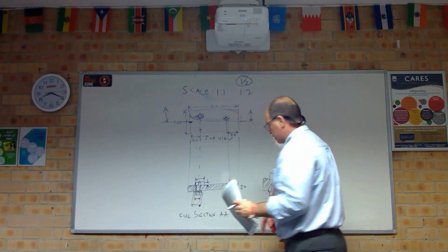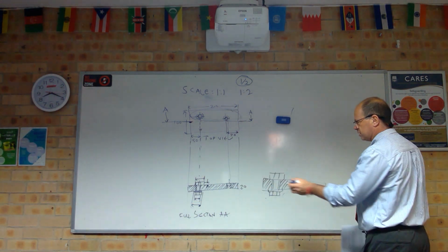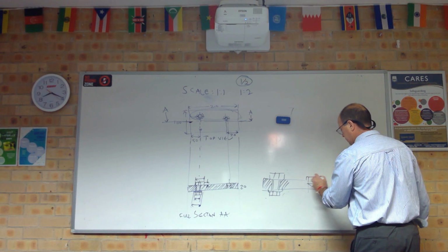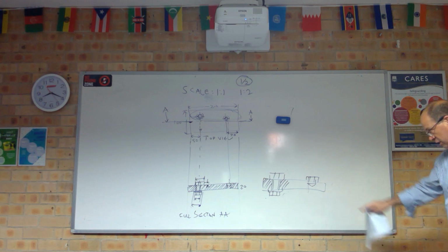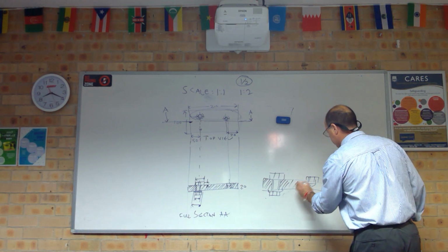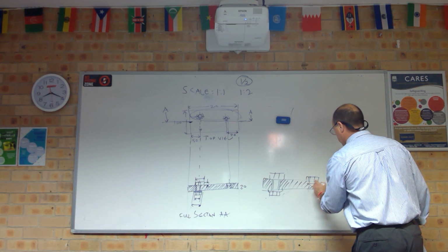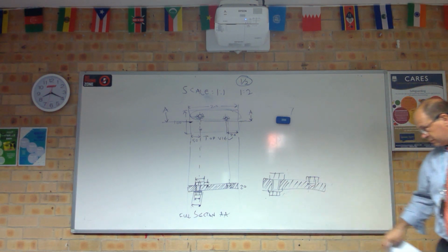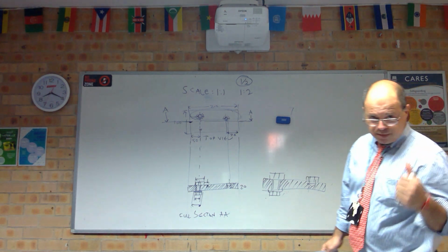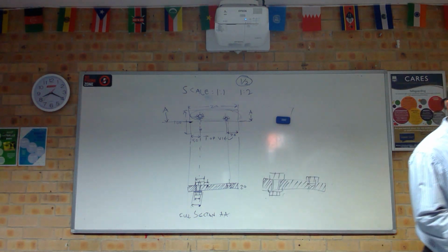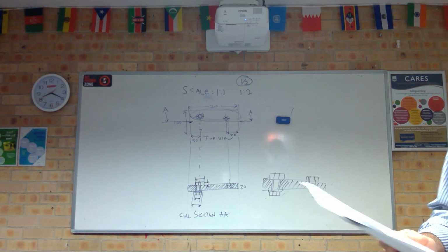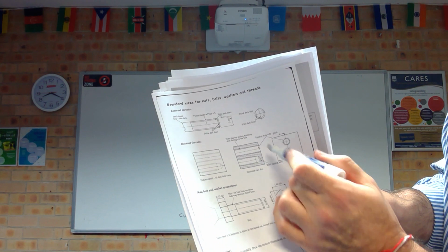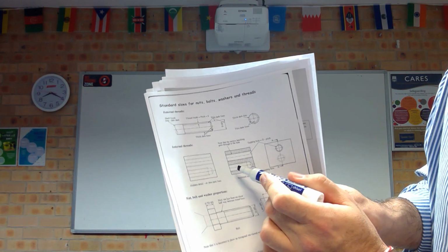So that is that part of the diagram. So you'll have this diagram with one will have a bolt in it that is not coming through, and then we hatch the whole thing. And once again, we don't hatch onto the bolt, the hole, or the thread lines. Okay, so this is practice at dimensioning and using that calculation that you are supposed to know. Okay, this is practice at knowing how to draw a blind hole and a through hole.